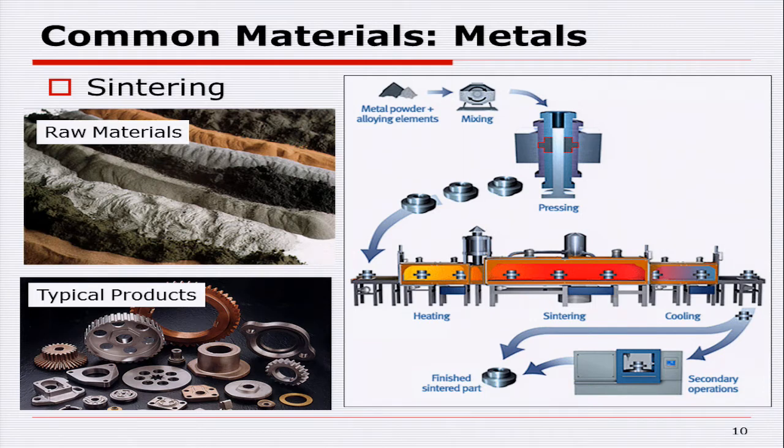This sintering process we'll talk about a little bit later when we talk about ceramics, but understand that your pottery, plates, things like that, bricks made of clay are manufactured in the same way. They are sintered. You bring particles together and you heat them to a high temperature, but not high enough to melt them.